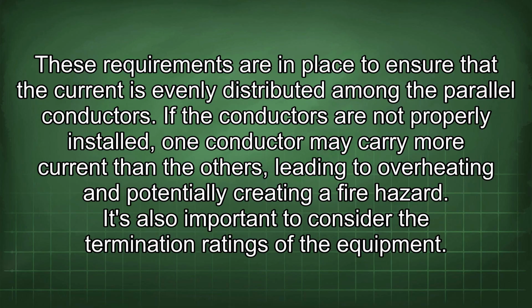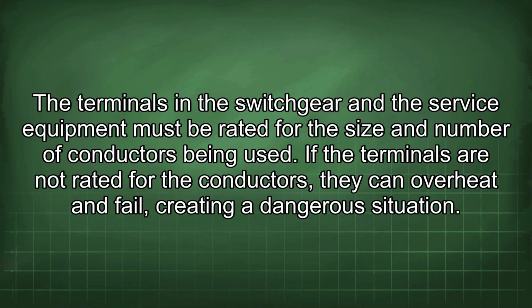These requirements are in place to ensure that the current is evenly distributed among the parallel conductors. If the conductors are not properly installed, one conductor may carry more current than the others, leading to overheating and potentially creating a fire hazard. It's also important to consider the termination ratings of the equipment. The terminals in the switchgear and the service equipment must be rated for the size and number of conductors being used. If the terminals are not rated for the conductors, they can overheat and fail, creating a dangerous situation.